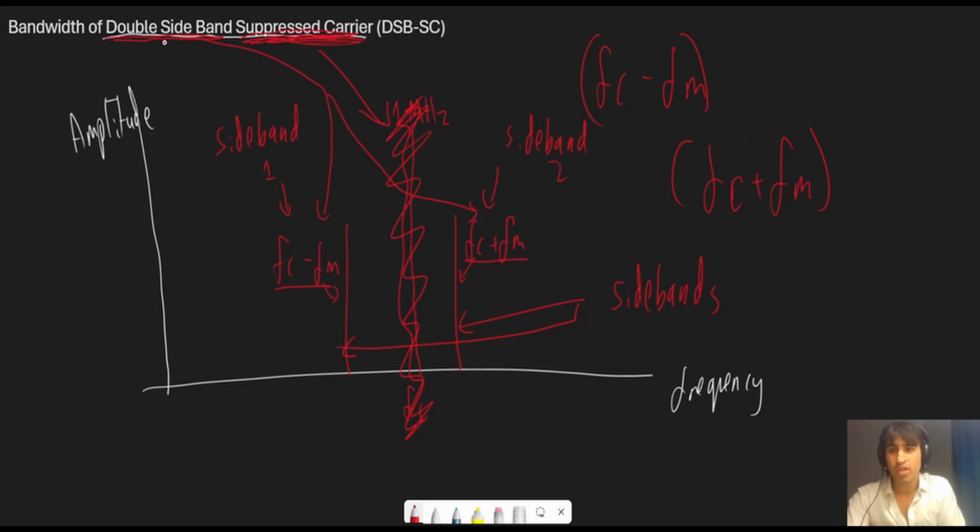That's where the term double sideband suppressed carrier comes from, or shortened, DSB-SC, which I will commonly use. You might be asking yourself, doesn't that mean we're duplicating data? Yes, you're right. In DSB-SC we are duplicating our signal.